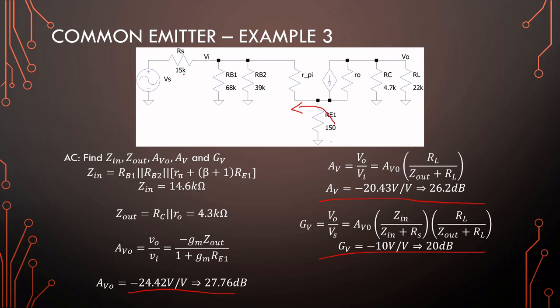And you can see in this example I used a much higher input resistor, and I used a much higher load resistor. So with the output impedance here being low and the load being a high value, the loading effect is not so bad. Okay, and same with input, since we have an increased input impedance, our loading effect will not be as bad into the amplifier as well.